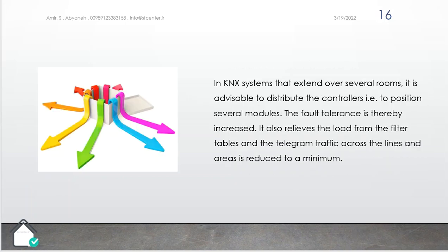In a KNX system that extends over several rooms, it is advisable to distribute the controllers to position several modules. The fault tolerance is thereby increased. It also relieves the load on the filter table, and telegram traffic across the lines and areas is reduced to a minimum.